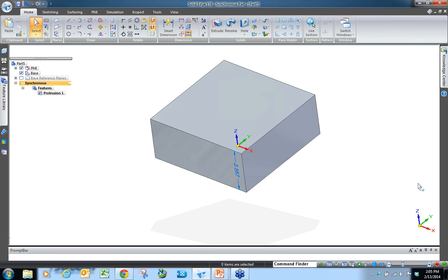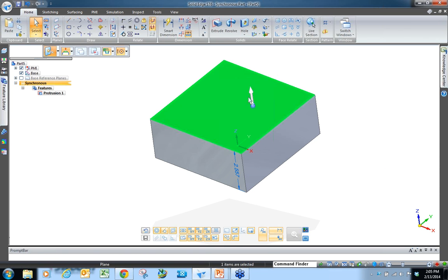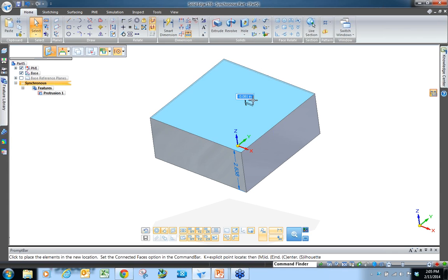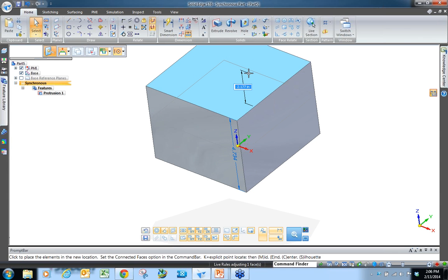Why? Because everything I do from here on out is done to the actual 3D model. So if I want to make it taller, I can just click on the face, and using my steering wheel, I can stretch that face out and collapse it back down.